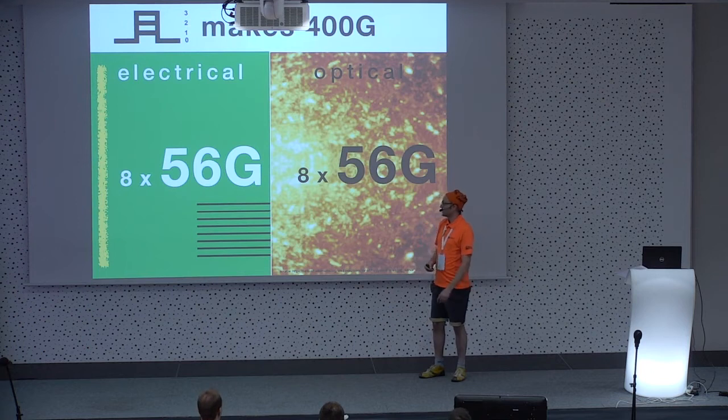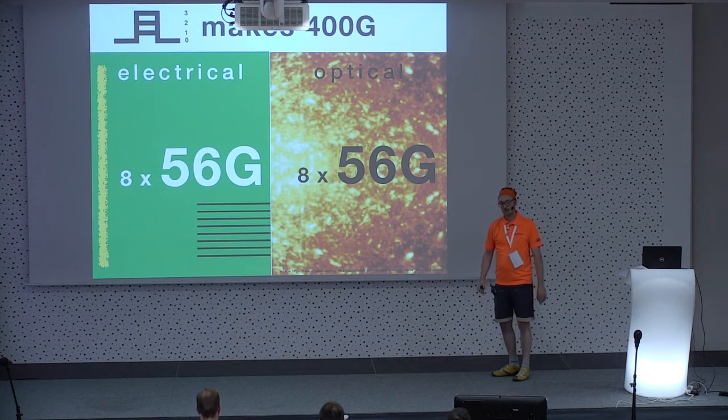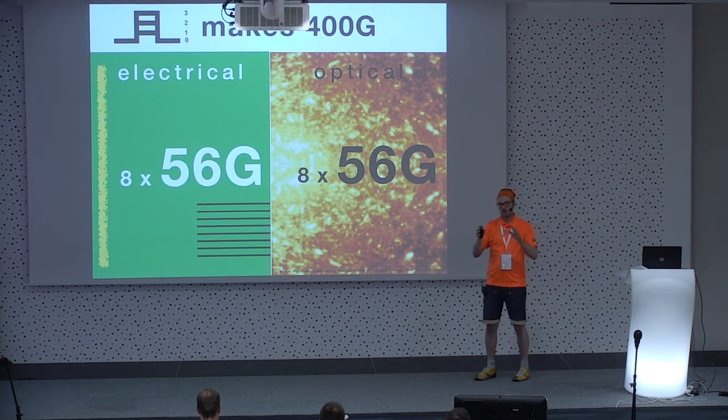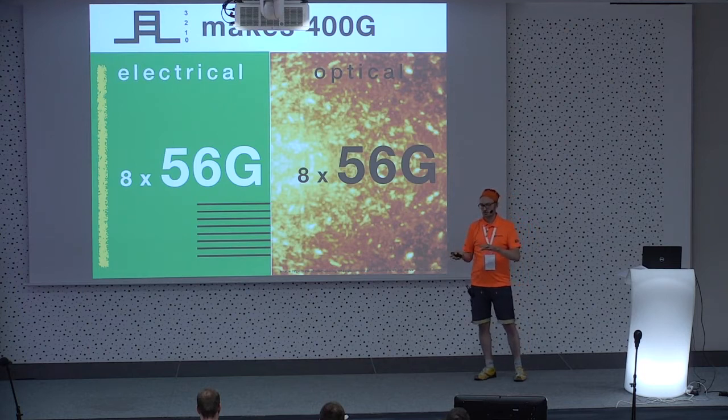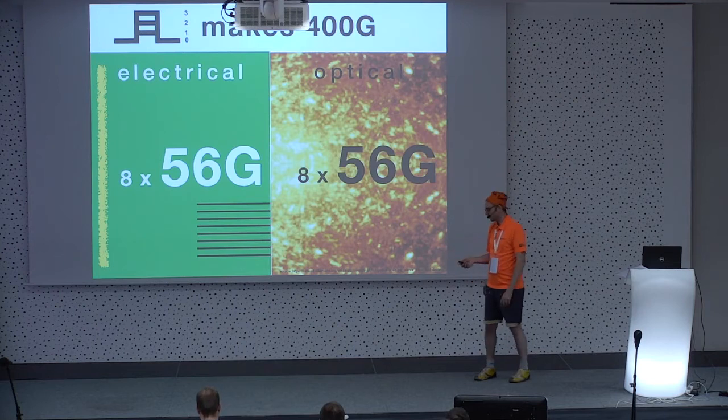Now coming over to the optical side, this will be the first generation, also having 8 lanes running on PAM4 with 56 gigabit, basically 8 lasers on a speed of 25 gigahertz, modulated with PAM4, getting out 56 gigabit for each laser. I don't mind now, or don't discuss if it's a multi-mode or single-mode transmission. At the end of this day, it's the same theory behind it.